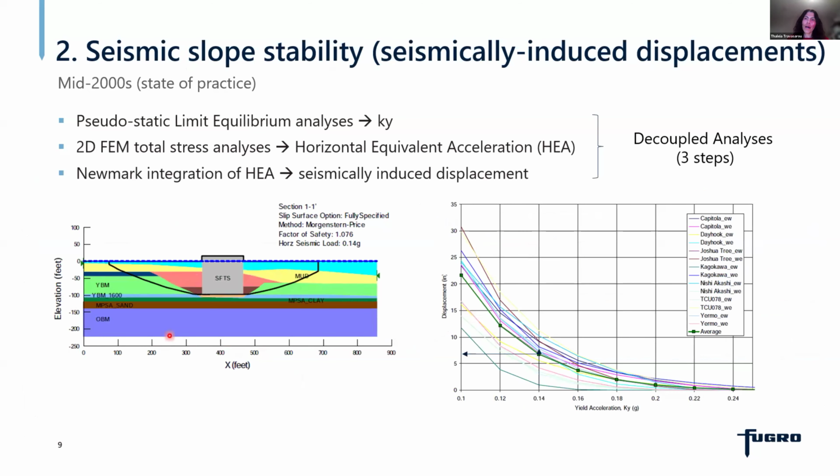So looking now at the seismic slope stability and the associated seismically induced displacements, to the west of the tunnel, where it crossed the shoreline, the ground was sloping, and the tunnel is surrounded by soft young bay mud. And so the key question was, was the seismic joint, which essentially was between that transition structure and the immersed tunnel, appropriately designed to accommodate residual seismically induced displacement?